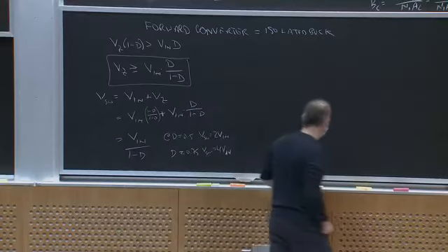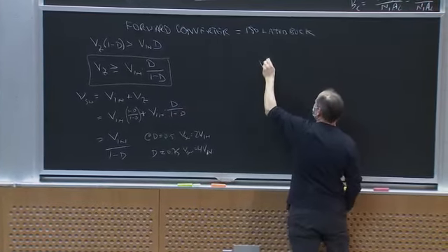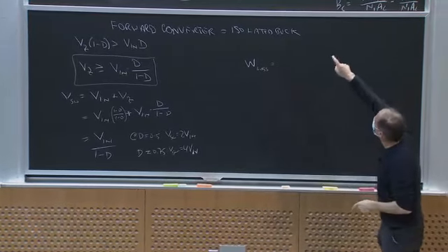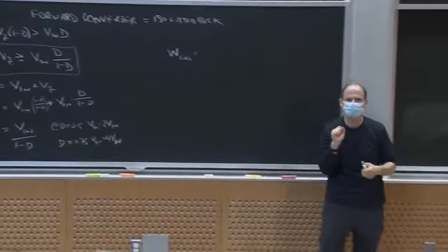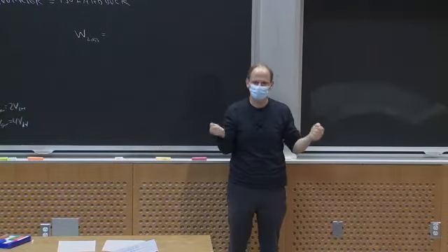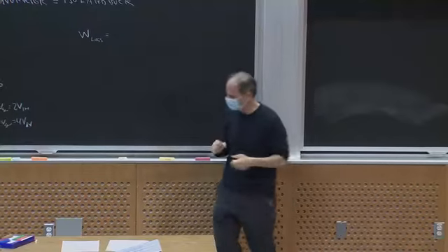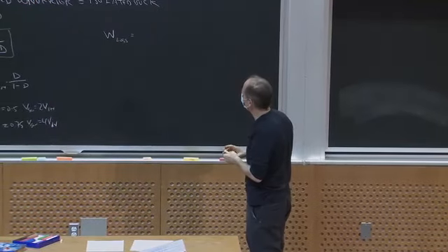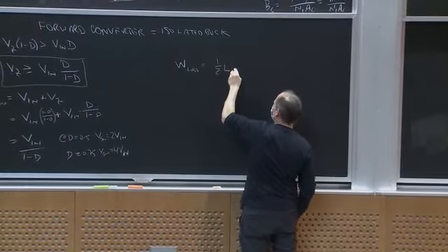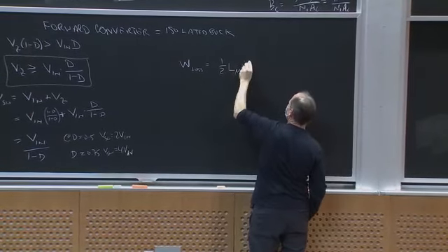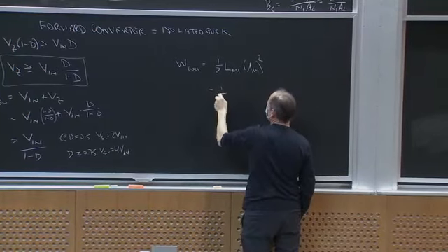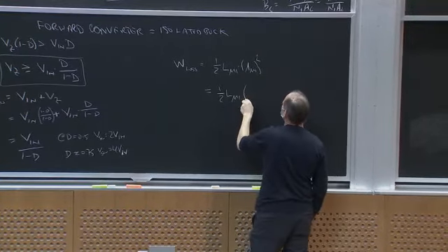Well, how much energy do I dissipate? And by the way, this process of driving the magnetizing current back to zero is called resetting the core. Okay, how much energy do I lose in resetting the core back to zero flux density? Well, that would be 1/2 L_mu1 times I_mu1 squared. What's I_mu1?